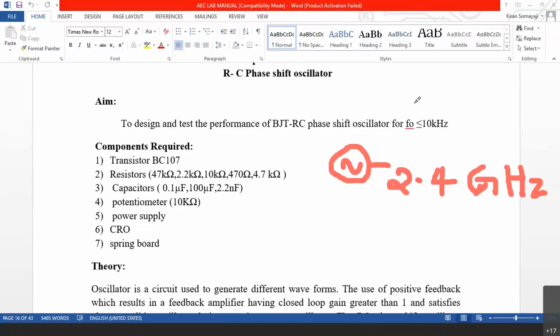The amplifier along with the feedback network is now a closed loop circuit. That closed loop system takes its own time to stabilize. In the sense, as soon as you switch the power on, the transistor will not come exactly to the middle of the active region. It will take some time. Until then, there will be some minute switching noises inside the device itself. Now, these noises also get amplified in the beginning.